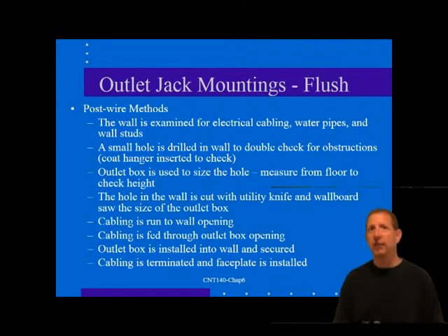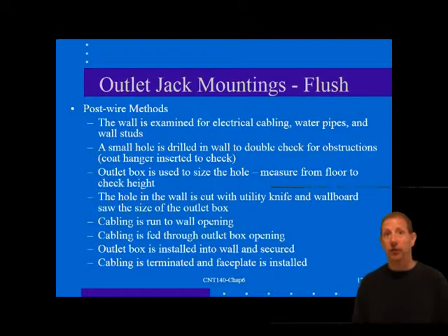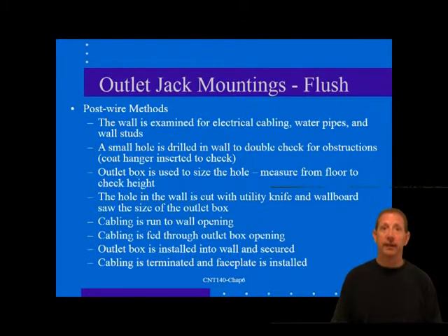Another technique is to leave a pull string in the wall during the rough-in. Place it in a hollow wall or inside a riser that connects to the outlet box. The outlet boxes have vertical risers or conduit that run from the top of the box to the wall's top plate and a half foot or so into the plenum space above the ceiling grid. Pull string can be run through a conduit to assist in cable installation. If a mounting ring is used for the outlet, a pull string is particularly convenient.